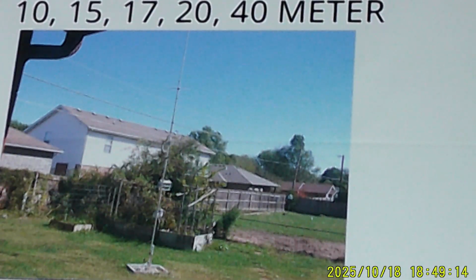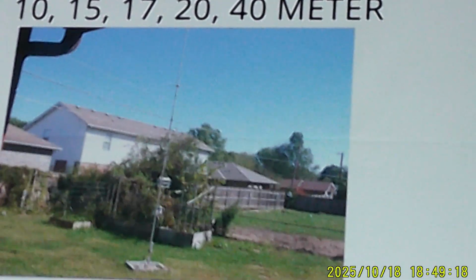When we first started, I put up a vertical antenna without any radials. It was an MFJ 19 something or another, I don't remember exactly. The antenna was built upside down. The feed point was at the top. And that antenna did a pretty good job. Eventually the wind did get to it. But the book says you need radials.